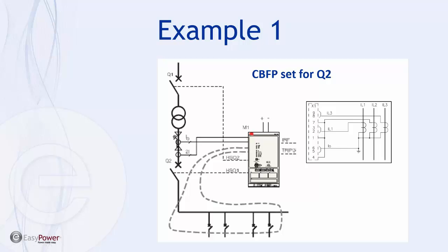If you have a breaker failure on Q2, then after a pre-programmed delay, high-speed output contact 2 will operate and trip breaker Q1 or high side circuits, which adds a little bit of incident energy due to the delay. Let's go ahead and see how we set the switches for this application.